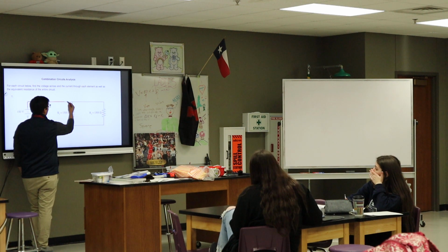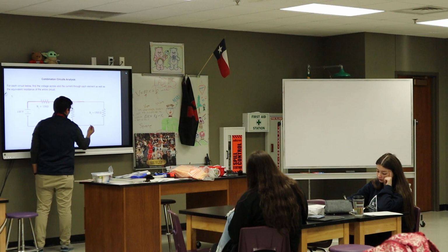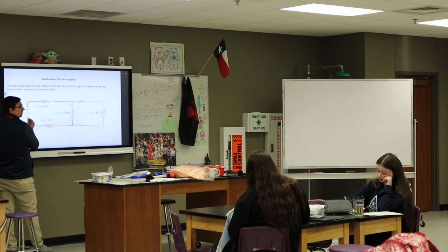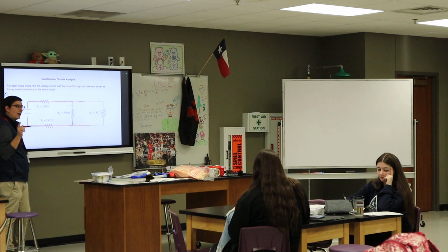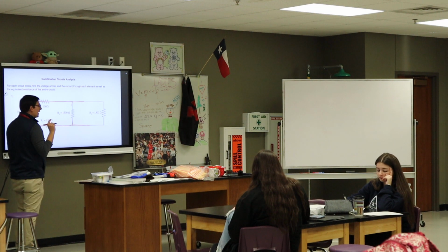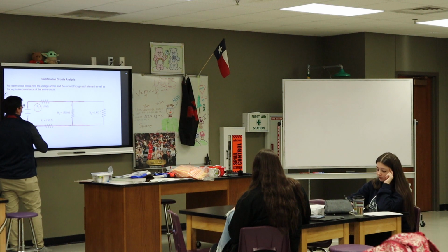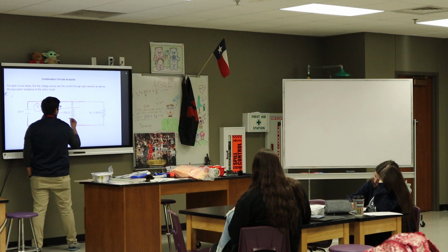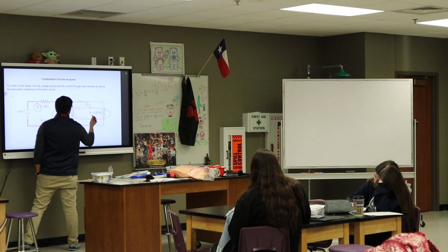And then if I keep tracing it, now I can see where I'm splitting. I can see that it's going to come back together on the other end. And then I've got another element in series. So when I look at this circuit, if you just trace the current, what I'd like you to see is, what I really have here is I have this resistor 1 in series with this parallel component, which I'm going to call RP, which is in series